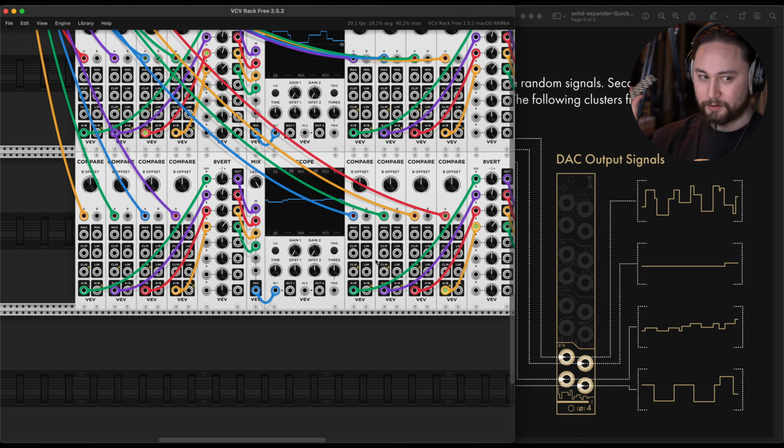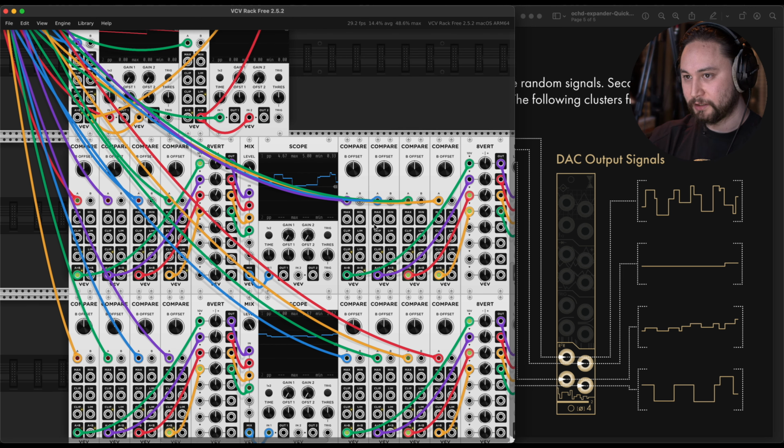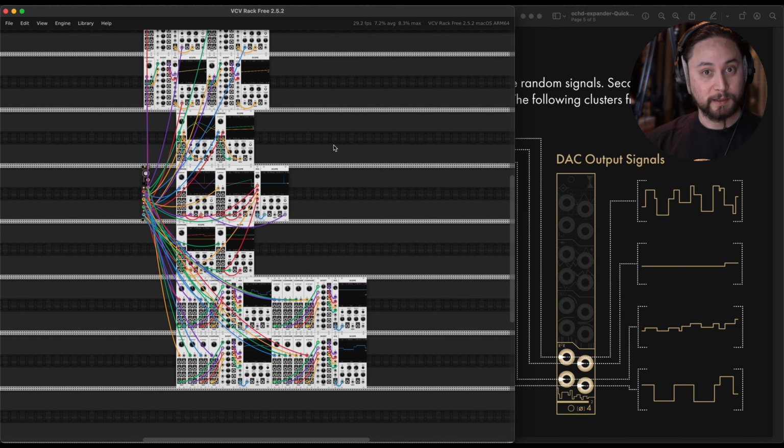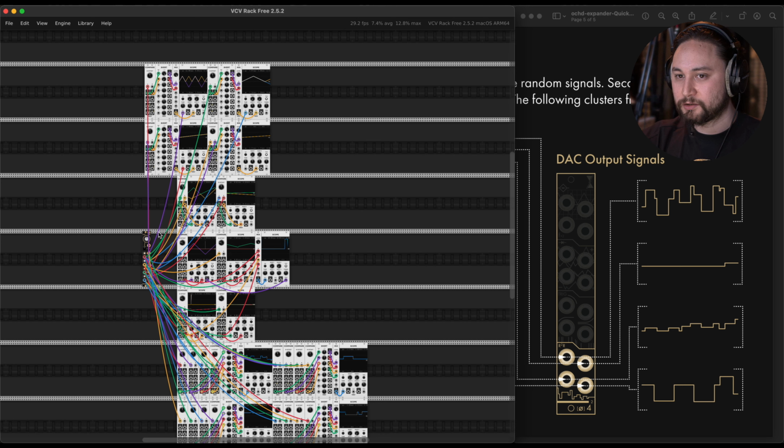So that's where the Oct expander itself really shines, is how much I was able to condense this down and get this efficient, because I really didn't want to go too far with the design of this for an expander for the Oct and add things like VCAs or sample and holds. The challenge was using as much of what exists as possible in very efficient ways, and I think I managed to strike a good balance of additional modulation output sources derived from these existing 8 analog LFOs.